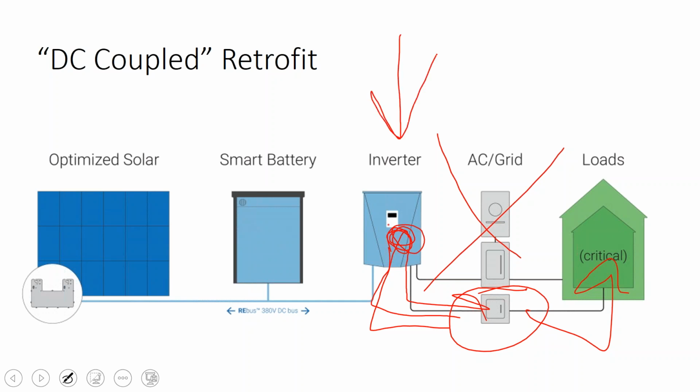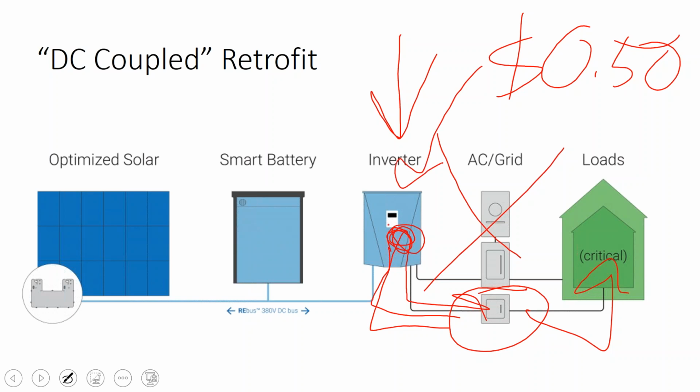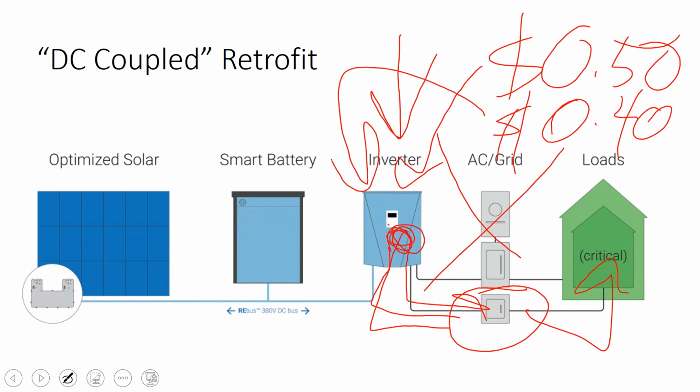Now, there's a company in Portland, Maine called Pika. It's a Pika inverter. They're a startup, and I've never used their product. They seem really small to me, but they're taking advantage of saying, well, we don't need a full-blown off-grid expensive inverter, where the system might cost around 50 cents a watt, which is high for an inverter budget. The Pika inverter may have fewer functions, maybe designed only to get you through a 30-minute or 60-minute blackout, not powering your whole house, but just powering critical loads. But it also drops the price of that inverter.